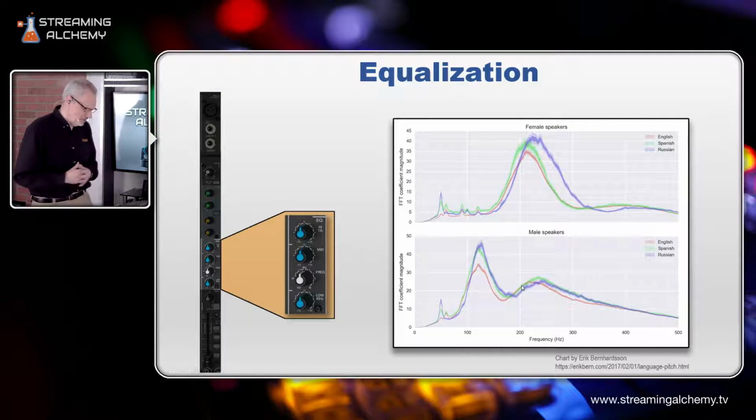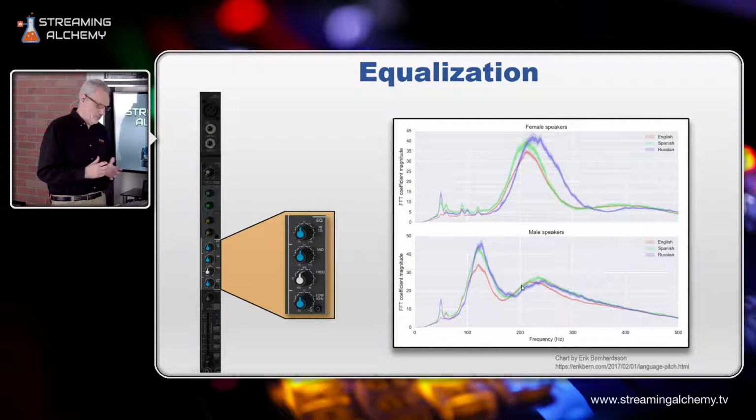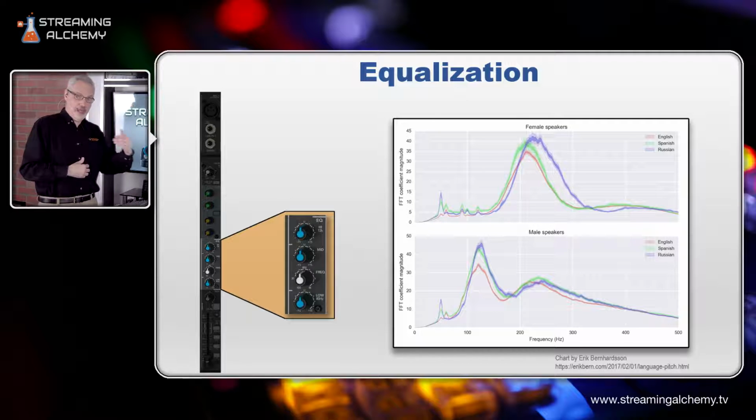The other thing to consider is that even though these sections here may be the peak in terms of vocal energy coming out, all the intelligibility, the things that let you understand sound, come from a lot of the higher end frequencies that go along with it. So the articulation points in different types of letters and phrases that people use all depend on higher end frequencies.